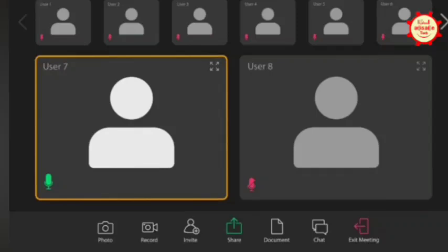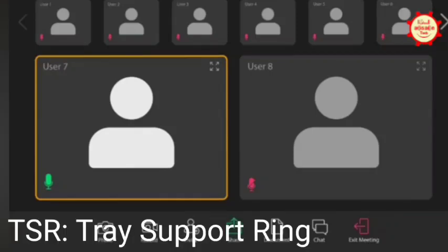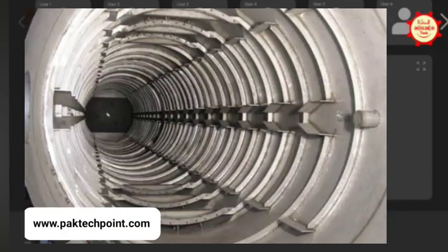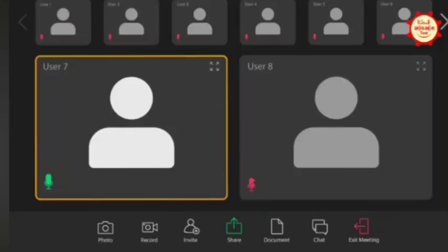Yeah, varieties will be there, but Kaushik, you are talking about TSR. TSR support will be common, and the tray inside, the bending and the holes where the fluid passes, that design differs. But in the TSR also there will be differences, for example the width of the ring. Sometimes only 30 mm width. It depends on the weight it has to carry and how much fluid is stored on that tray, and so on.